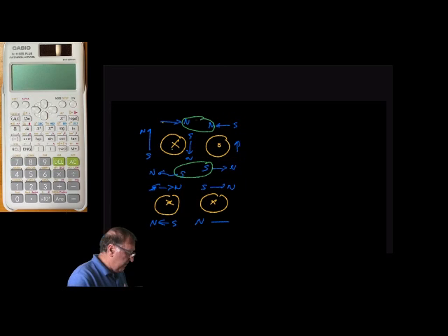That means the wires would be opposing each other and trying to push apart. In the second example, we have them both going into the page, and now the north and south poles are together, which will attract each other, so the wires will tend to pull together.